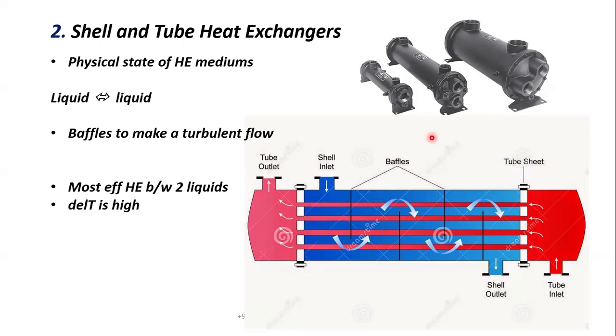And in order to do that, we might need to use something called chemical flushing. That means we pour some chemicals which will remove the dust and rust particles, especially the scales, from the inner surface and inner walls of the shells, and even the pipes also. This process is termed chemical flushing.